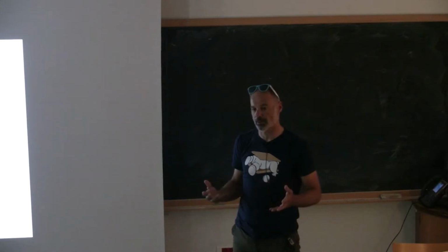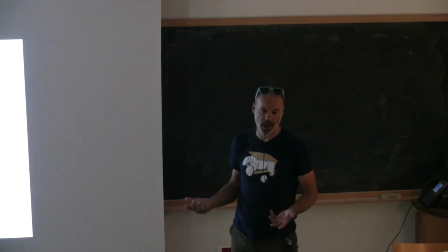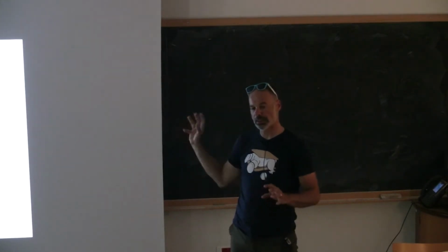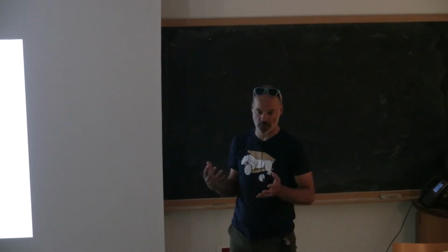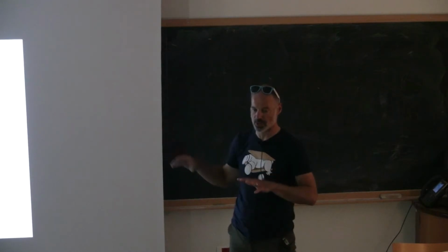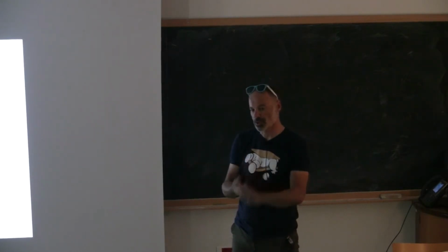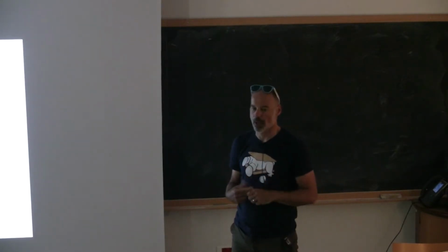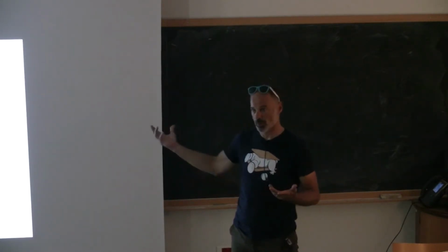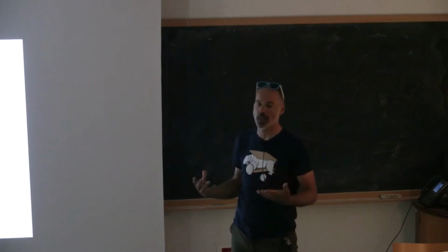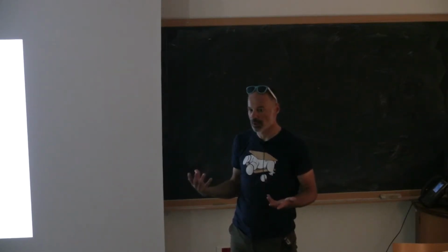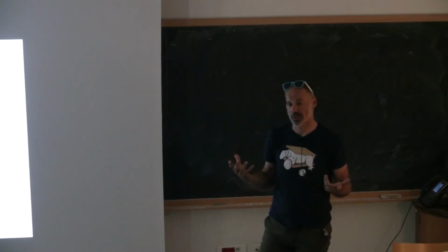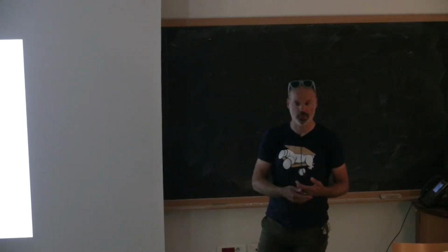But I think that, of course, sorptivity matters, all the terms are important, but I think the leading behavior is saturated hydraulic conductivity for these kinds of systems. Now, part two of your question further reinforces why our models work at larger scale. I think what we're seeing, we don't really see a lot of quote-unquote Horton runoff. And if you start to look at the more modernized literature, it looks like most of the water takes a path through groundwater, most of the snowmelt takes a path through groundwater.